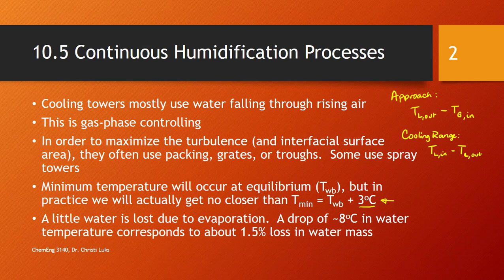The minimum temperature would be equilibrium, but that would require an infinitely large tower, so in practice we're not going to get any closer than 3 degrees C above the wet bulb temperature. And we're also going to have to worry about water loss due to evaporation.